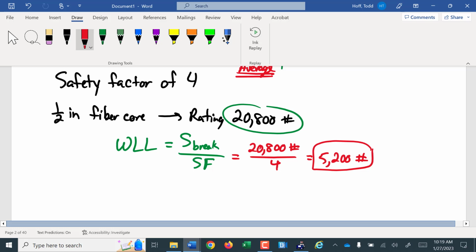So what happened there was they used their safety factors twice, their safety margins. When they inspected the bridge for wear and tear, they said, yes, it's weakened, but the safety margins will make it safe for use. And then they went on top and threw the construction load in there and said, oh, the safety margins will allow us to put our construction load on here. The overlap caused it to fail. So yes, a safety margin of 4 or 5 times seems extreme, but there's one where a 12 or 15 safety margin did not cover all those extreme circumstances that came together.